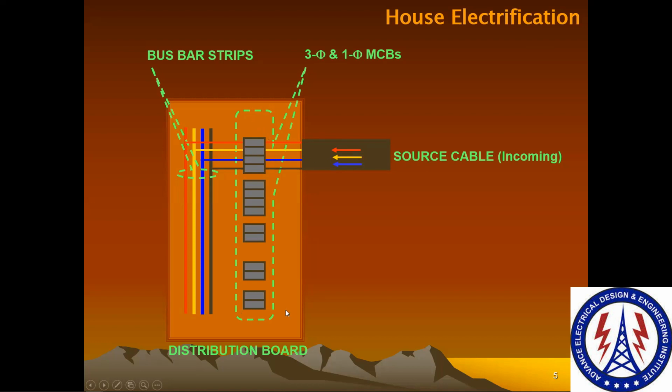First we put an MCB before entering the power. Why are we putting this MCB? We are putting this MCB to protect our complete distribution board, in case there is some unhealthy condition on the outer side of this DB. So that unhealthy condition will not enter into the distribution board, which could make it unhealthy as well.